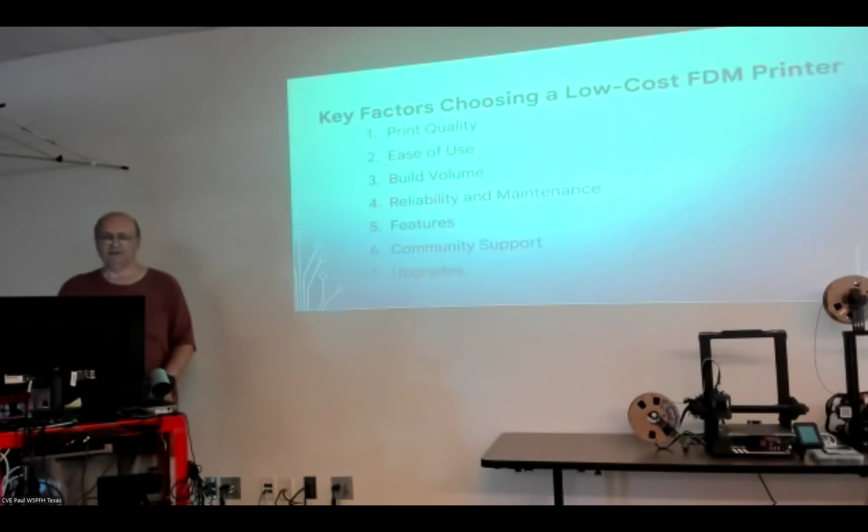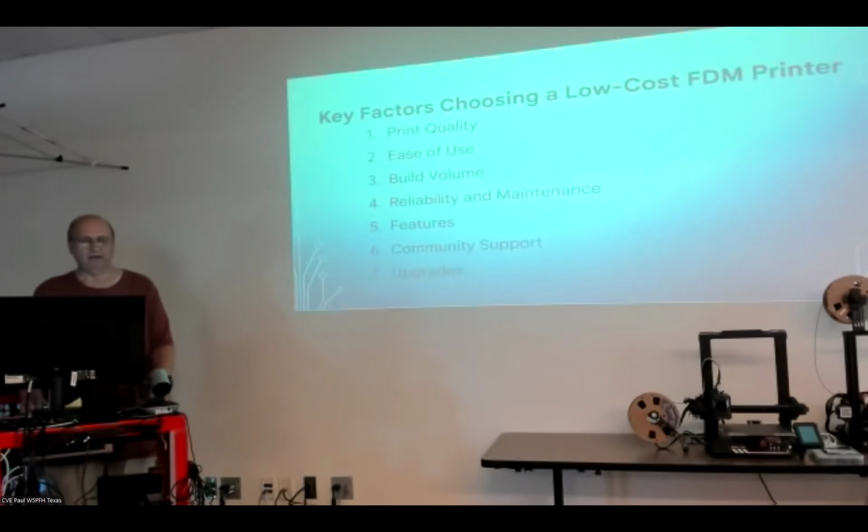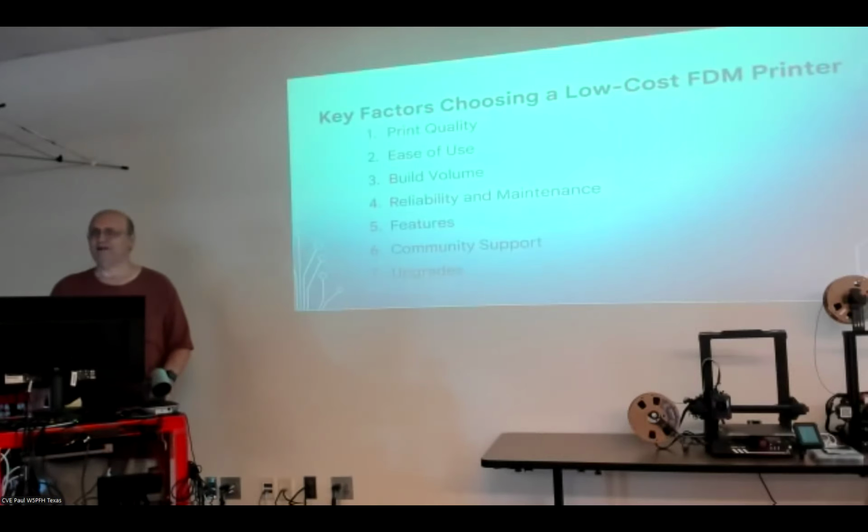So, key factors in choosing a low-cost FDM printer. You want to look at the print quality. How easy is it to use? Is it a pain to set up? Do you have to level it every time? Those kinds of things. One of the things that I ran into was build volume. I had a piece that I wanted to print for a scanner, and it doesn't fit on my bed. So you look at chopping it in half and putting it together after the fact, or find somebody with a bigger print bed.